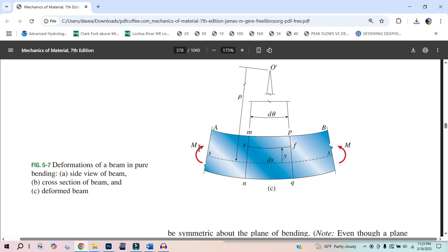This can go a long way in statics and material mechanics: every time you see a moment, just put a force this direction and a force this direction, and you choose the distance. It'll be more accurate if that distance is closer to this point S, and these forces are bigger to accommodate that.